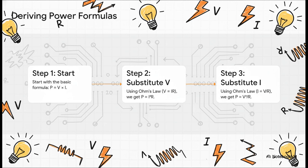It's a very simple substitution. We start with P equals V into I. Now, from Ohm's law, we know that V is equal to I into R. So let's replace V in our power formula. We get P equals IR into I, which gives us P equals I squared R. Simple, isn't it? Now, let's start again with P equals V into I.